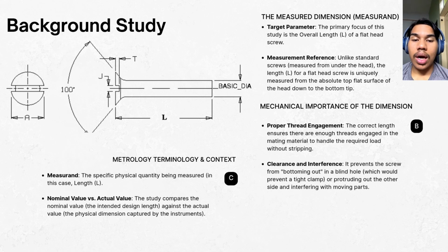And the second one that will be our concern is about the protruding out. If we screwed and the hole is not enough, the thread is not enough, and there's some sort of clearance interference between the thread of the screw and the object, then the material that we made will cause the screw to protrude out. So this will be a big concern, because if the screw protrudes out, it will likely have a high chance to clash with the moving part of our machine.